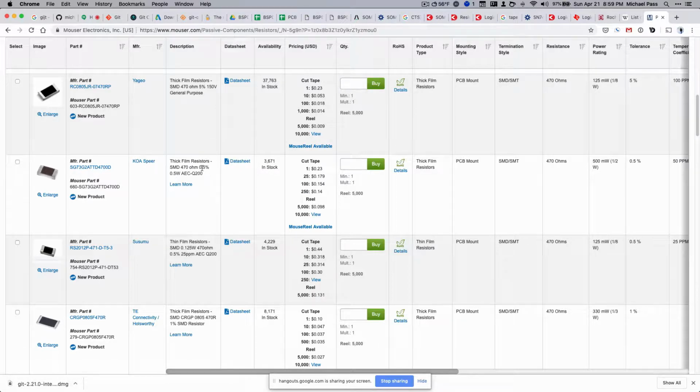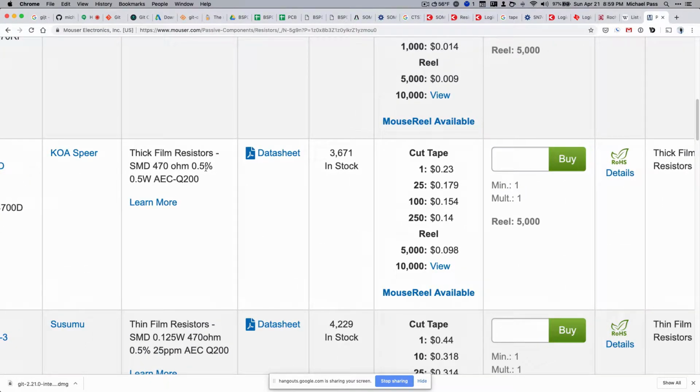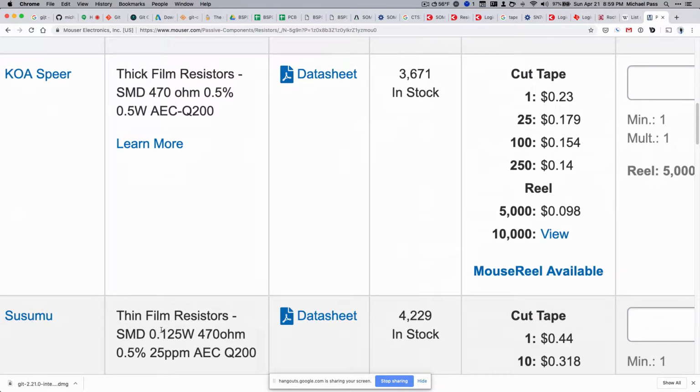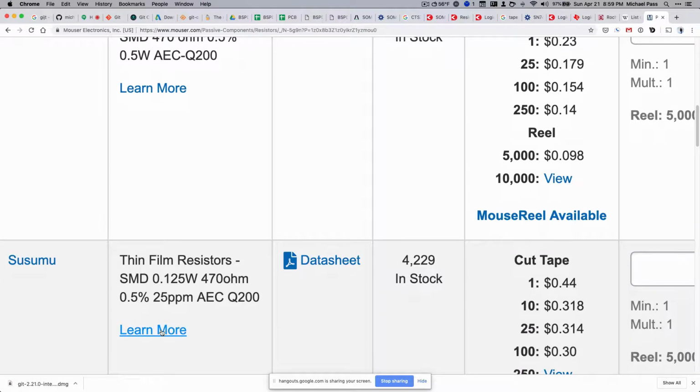Now you can sort, since they will have some differences. Ideally we would like them to be as accurate as possible. Just ask me if you have any questions over these. They need to be rated for certain things, but for most of these resistors it's not a problem. We've basically picked out all of the resistors that matter, but the different variables are how much heat it can dissipate, meaning it matters how much current is going through it.